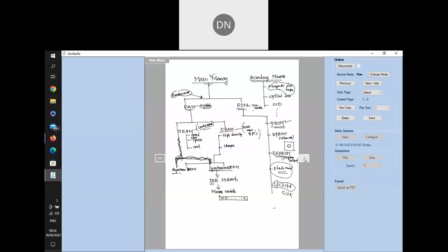So all the memories used in embedded systems, in the SD card and the pen drive, are of the type called flash memories nowadays. The only thing is reading is possible randomly, but writing has to be done a page at a time. You need not worry about this because it is taken care of by the low-level drivers. When you are developing drivers at the low level, then you should know how to write it, what the page is, how to read an address and all those things. It's very interesting to write a driver for a flash memory chip. So these are the types of read-only memories available in the market.